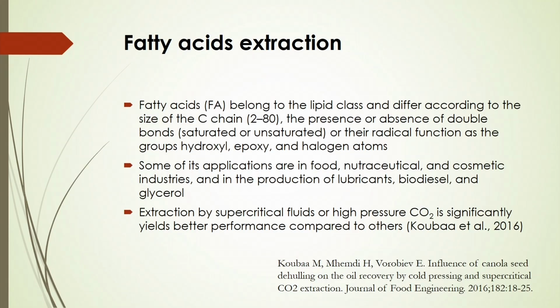So, that is why extraction by supercritical fluids or high pressure carbon dioxide is significantly used as a better technique to get better yields and performance compared to the other conventional processes. In that case, it also gives high performance of mass transfer during the extraction process to get these fatty acids without using any other toxic solvents. So, Kauba et al.